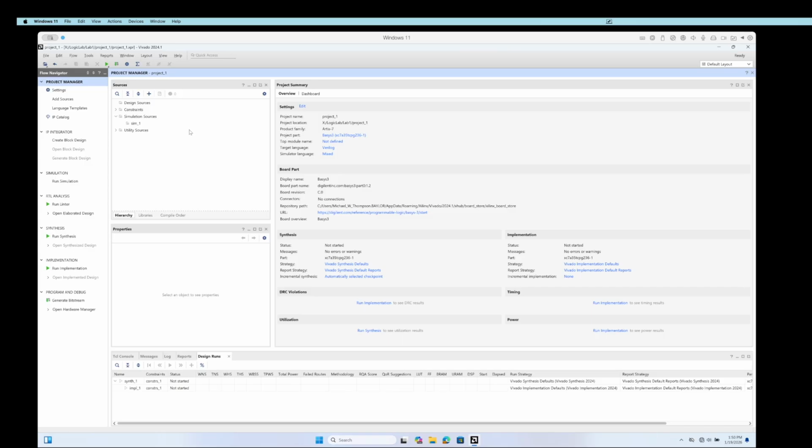Okay, so if you remember the pre-lab, you looked at the workflow for Vivado. You have design files, which we called RTL. We have test benches, which are simulation sources, and we have some constraint files. So we're going to add these in. The first thing I do, I try to do this systematically, where I get into a flow, because you're going to do this a lot of times, and you don't want to make mistakes, because if you make a mistake, it ruins that project and you have to start over.